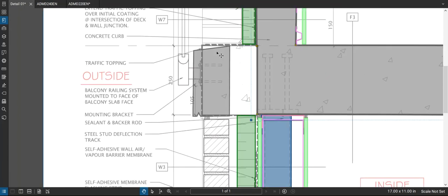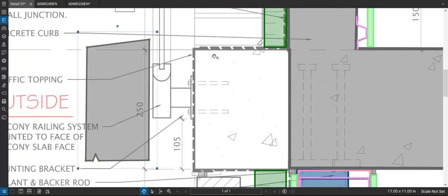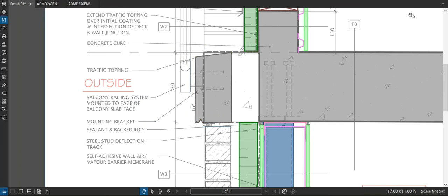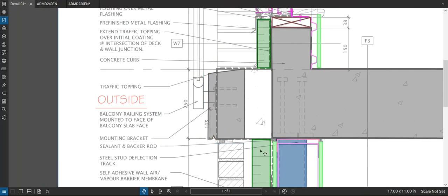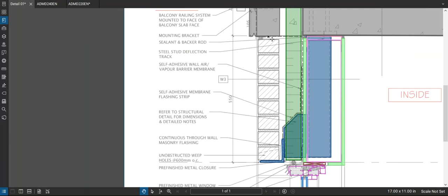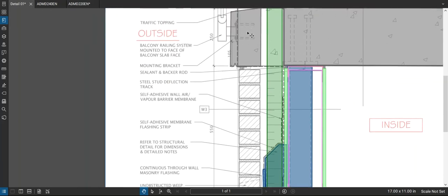So we'll deal with the railing here in a minute, but the other thing I've added to this as well, which I think was missing in the original design, is this flat spot right there. So don't make flat spots, just slope, get a slope. Drain, use gravity to your advantage and drain this thing. So I've also put a slope on the top of that precast concrete element. Anyway, so what this has done now is it allowed us to continue the insulation up right there.